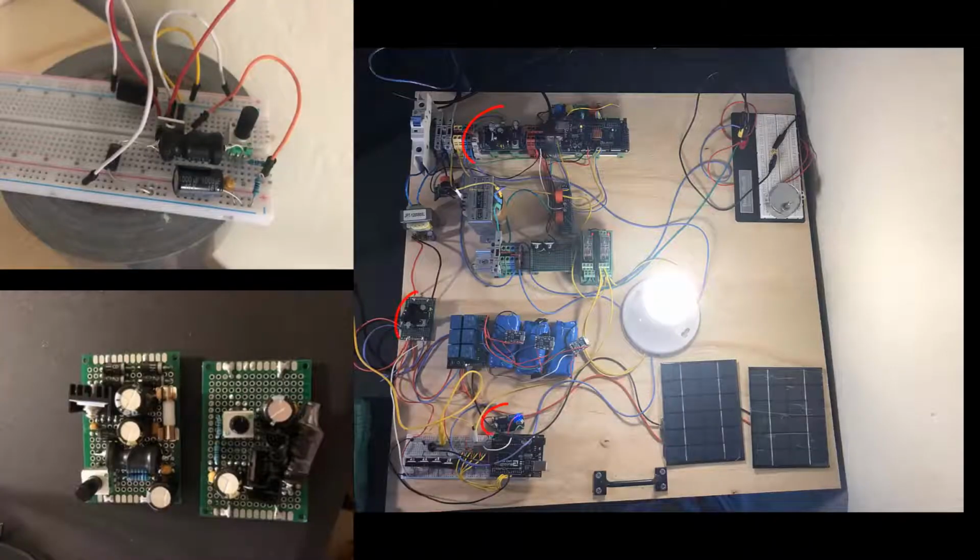The project calls for a 5-volt DC source to supply power to the Arduino and to power the battery bank alongside a solar array. Initially, we intended the solar array to charge the batteries alone, but realized we would need many more cells to supply the needed power in a realistic time frame. We implemented another buck converter to solve this issue. Here there are two buck converters.